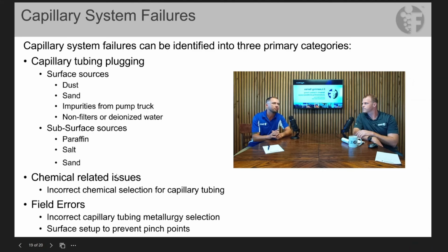So you've got to watch those things. It's very important to communicate with your chemical guys, making sure they're putting the right chemical to the right cap string to the right lease. So you want a cap tubing compliant chemical. For sure. And I've noticed temperature can have an effect too, where you almost dehydrate the chemical inside the cap tubing. If your pressure's not set right on your check valve and it's not doing what it's supposed to, it can just sit there and dehydrate, and now you've got a plug.